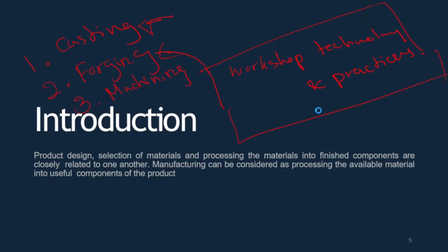I ask, what is casting? We take a liquid material into a mold cavity. Yes, we use molten metal and pour it into a mold. This mold consists of a cavity and we allow it to solidify into the desired shape. Using casting we can prepare engine blocks, cylinder heads in engines, and pump housings.